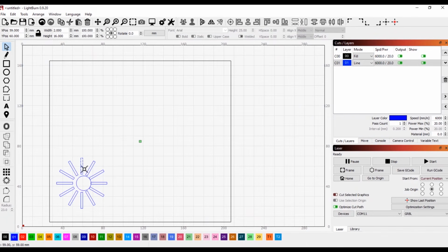So if I select this one first and then the circle last, it should bring the rectangle into the center of the circle. That's not what we want, it the other way around. So I'll undo that for now. And if I reselect them, but selecting the rectangle last, it should make that the center origin, and therefore it moves the circle into alignment with that.